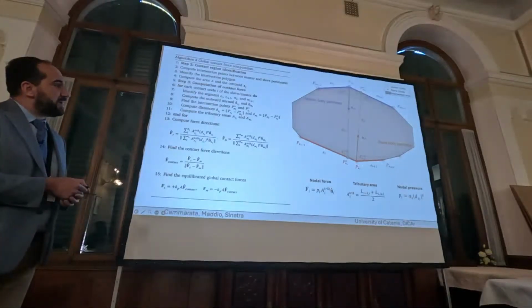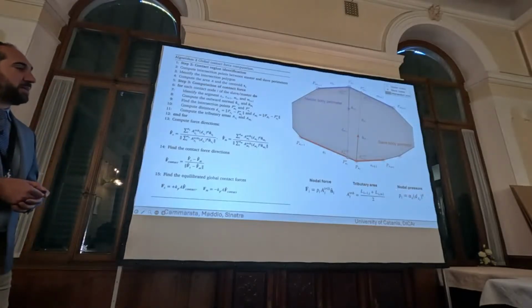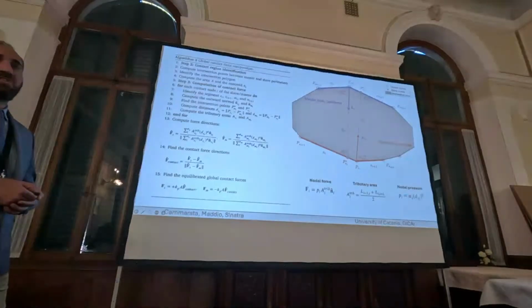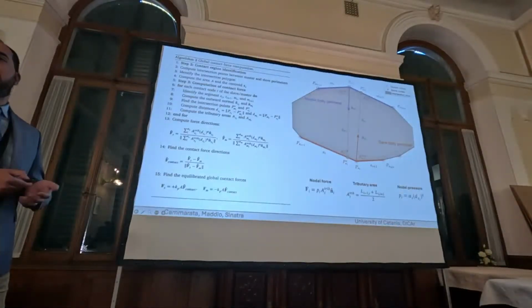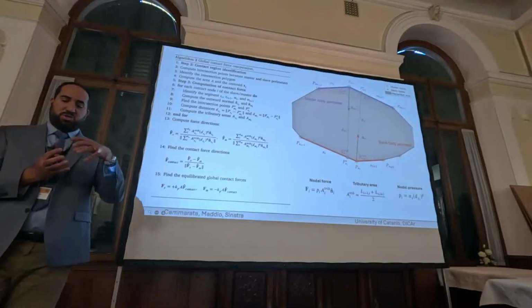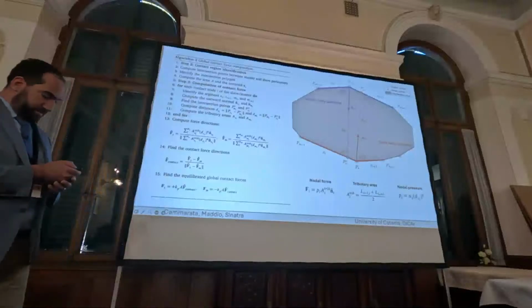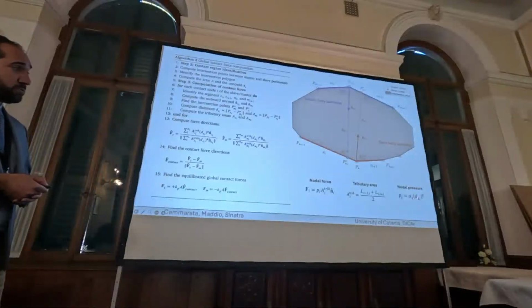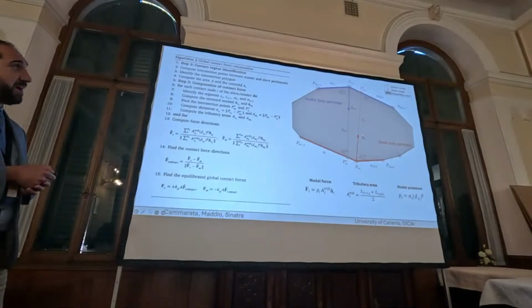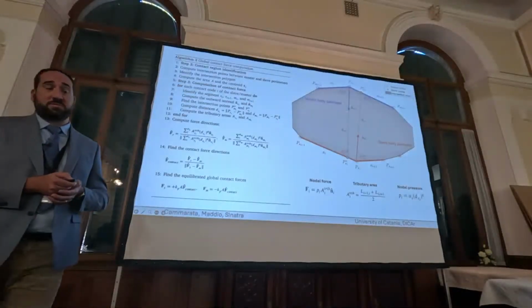We calculate these two lengths, and we calculate the tributary area. And then the nodal pressure is given by a coefficient that is a scale. So alpha S is something that scales the shape of the pressure distribution. And the pressure is also proportional to this distance that is found by means of a simple geometric scalar product.